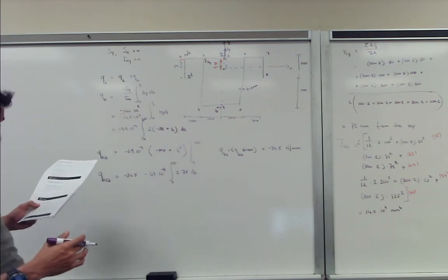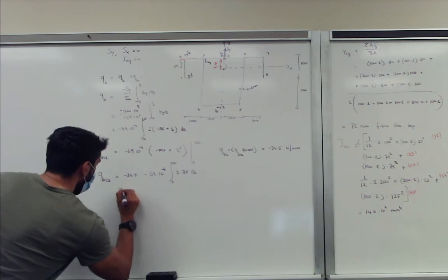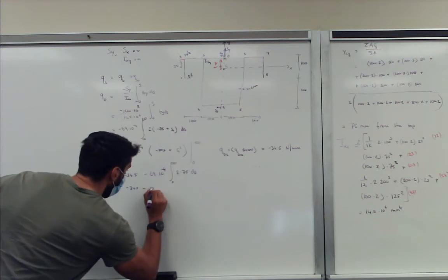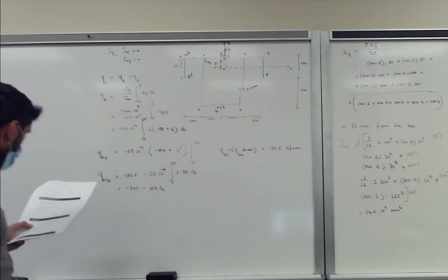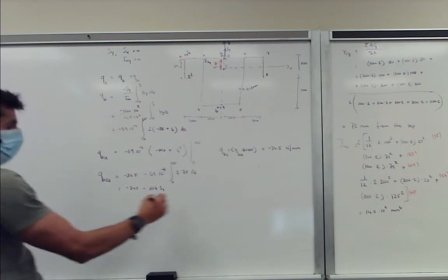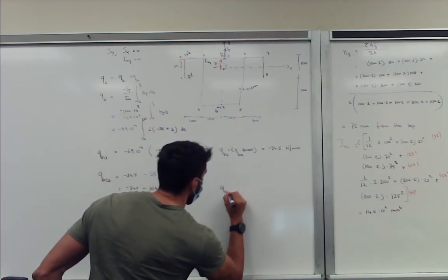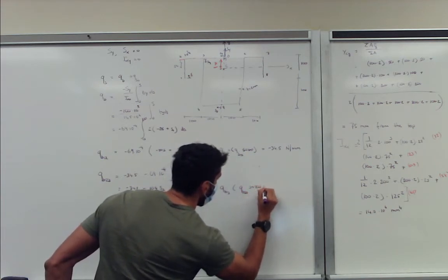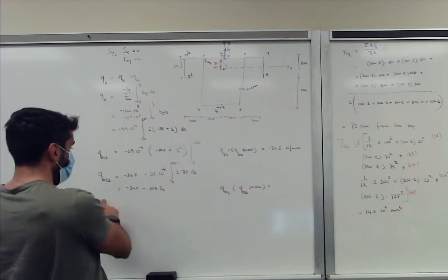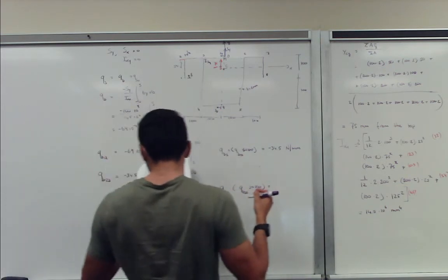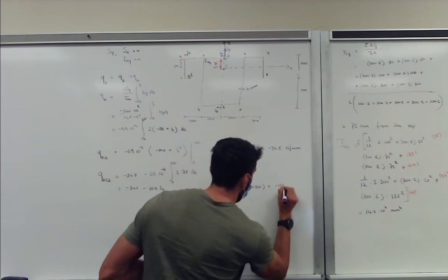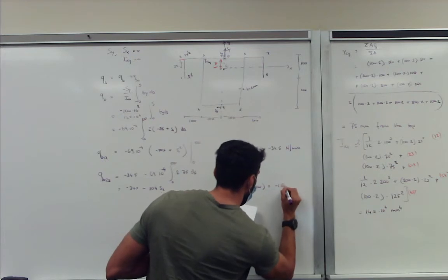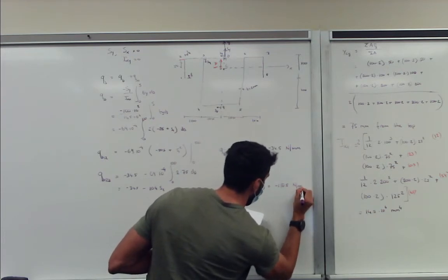So we can evaluate the integral. What we get is minus 34.5 minus 104 S2. Then we can fill in point 3, QB3, which is QB23 at S equal to 100. That's filling in 100 here and evaluating it. And then you get minus 138.5 Newton per millimeter.